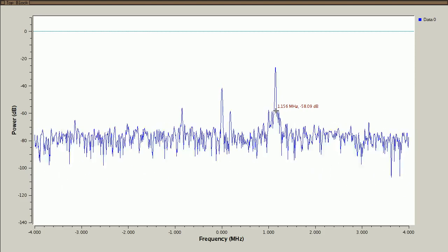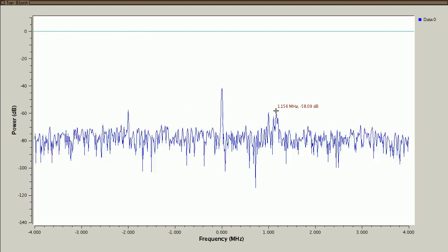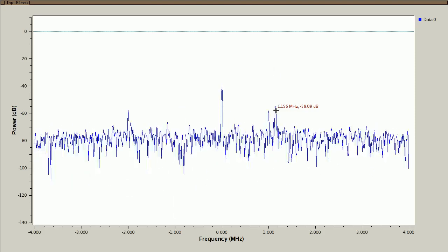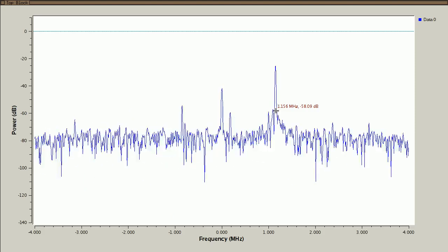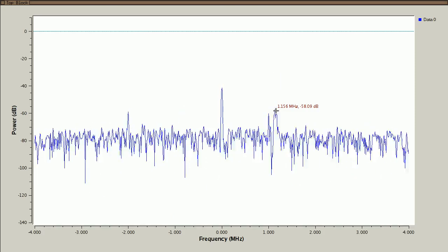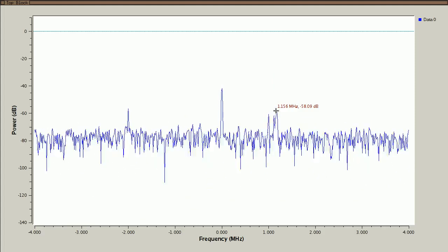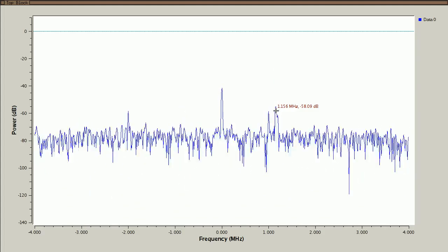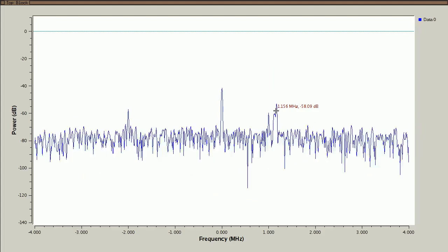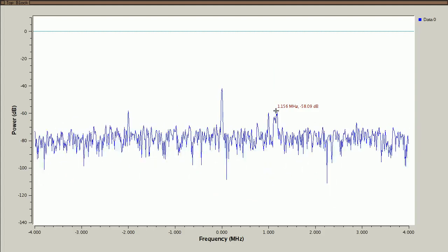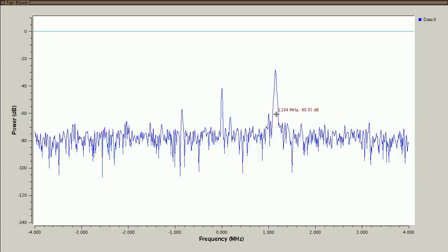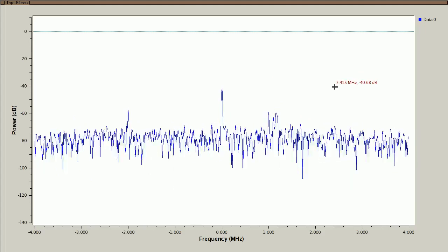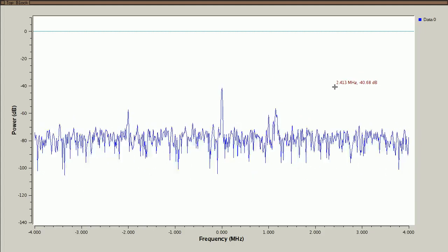If we had a very weak capture, if we weren't using very much dynamic range, then we have a fairly poor signal to noise ratio, and that means when we transmit, we're going to be transmitting a higher proportion of noise than we maybe could be. But if we were to recapture our signal in such a way that we use more of our dynamic range and have a better signal to noise ratio, then when we retransmit it, this noise here would be much lower in proportion to our transmitted signal. So we could be a better neighbor on the spectrum just by having a better capture in the first place.